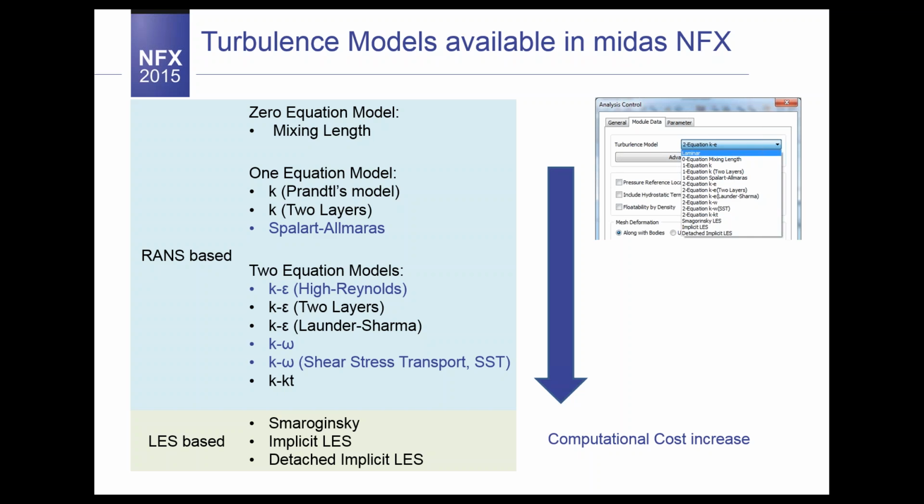But let's talk about this at this moment. As I said, the Spalart-Allmaras is very good for mildly complex external and internal flows. It is good for solving problems like the flow around airfoils, wings, ships, for example, but it performs very poorly for 3D flows. So it's not valid, for example, for flows with strong separation.